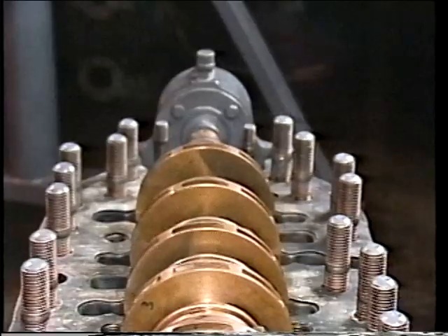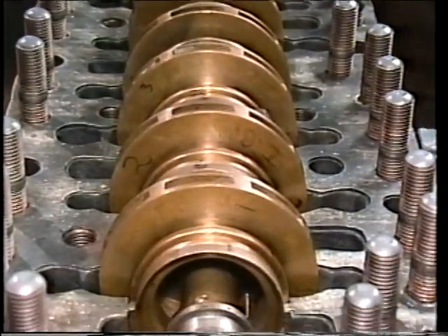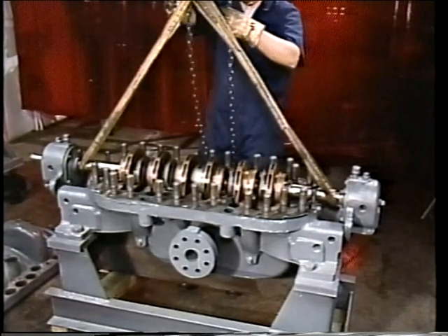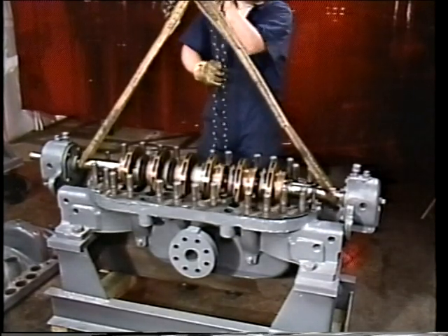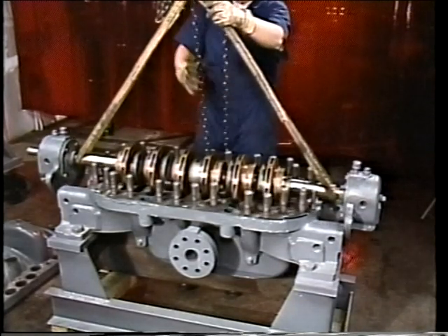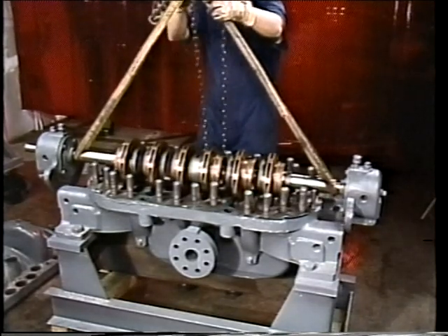Some equipment has more than one critical speed because of the number of rotating components present. For example, a single rotating shaft might have many impellers and collars. Each component would have its own natural frequency and critical speed, so it would be dangerous to operate the machine at any of the critical speeds.